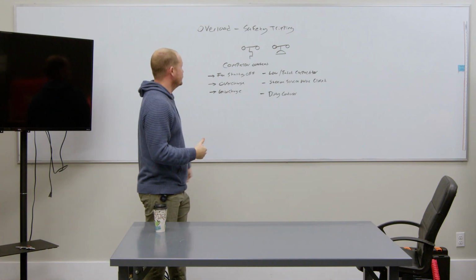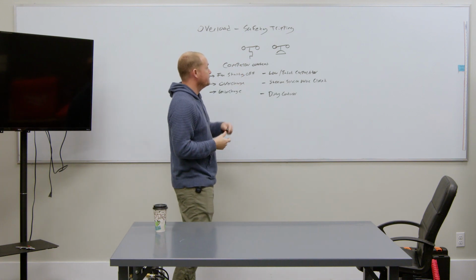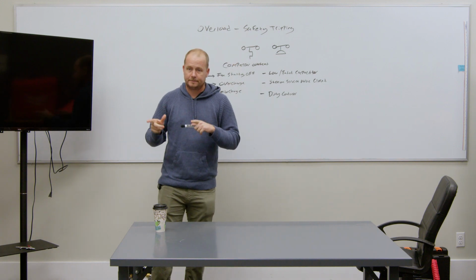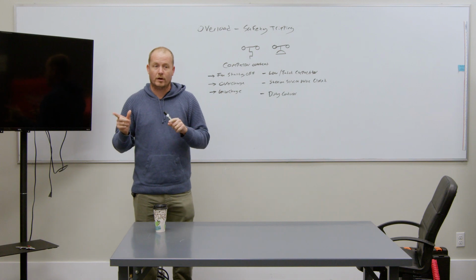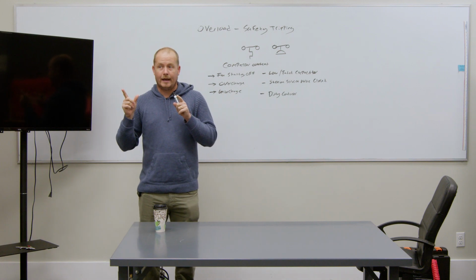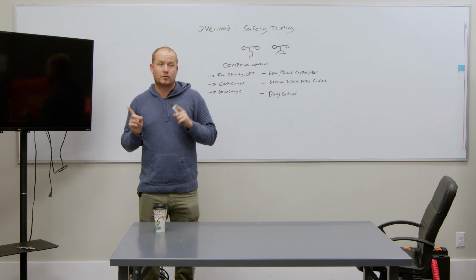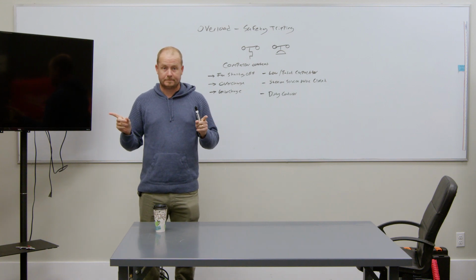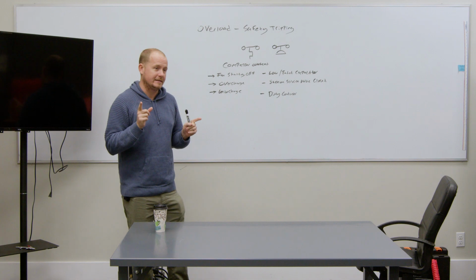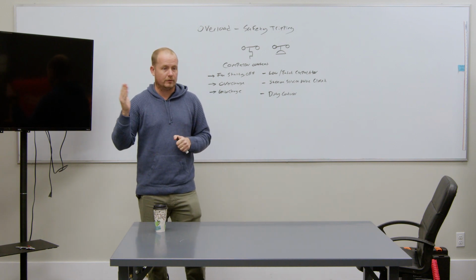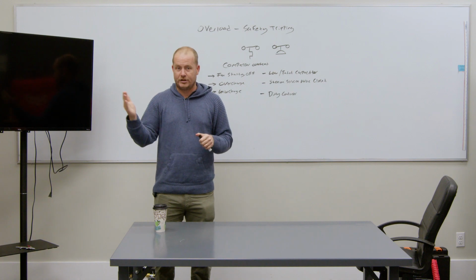But obviously first, if you show up, we're going to go back to compressor overheat. You show up, this thermal overload is tripped. Something happened that made this compressor run hot, and either it was really hot for a short period of time, or it was pretty hot for a long period of time. And that's actually a key distinction, because when you go up to a compressor and it's going in and out of thermal overload, like you can actually watch it happen.